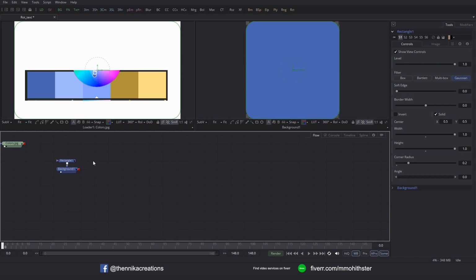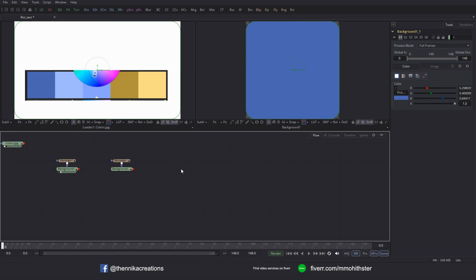Select these two nodes and Ctrl C to copy them. And then let's paste it 4 times. So click inside the flow here, Ctrl V, click here, Ctrl V, Ctrl V and paste one more time. Okay. Now let's change the color of these background nodes.